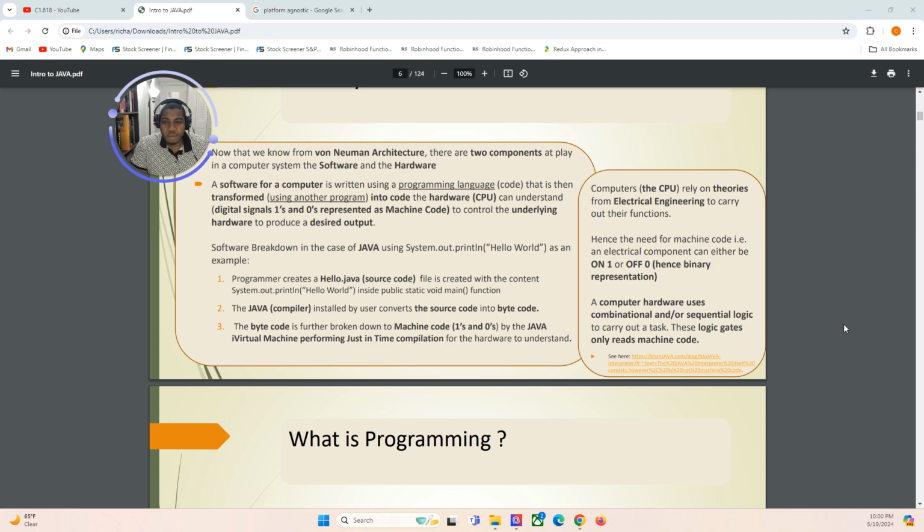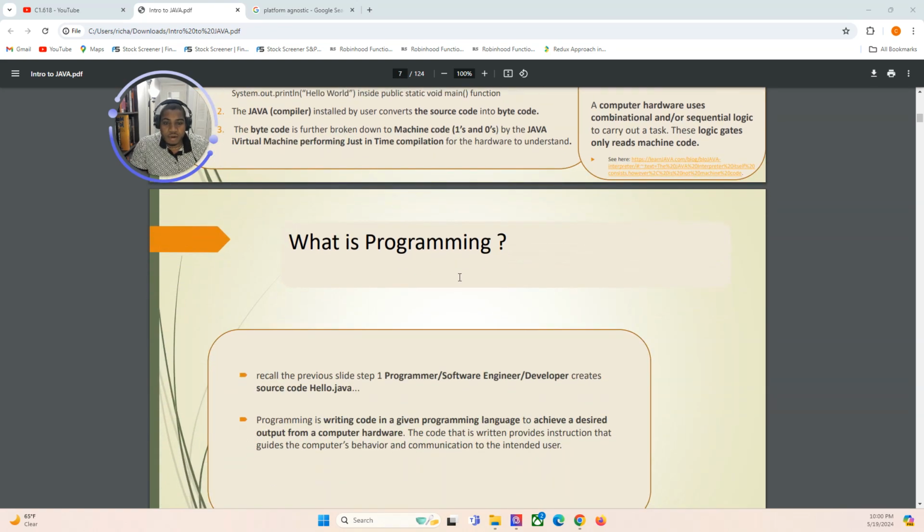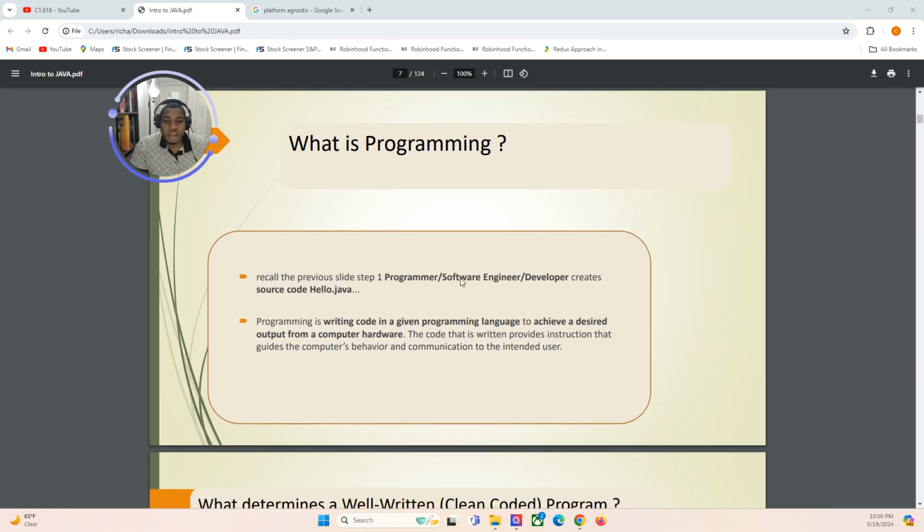And if we dig a little deeper, right, the underlying hardware is from electrical engineering theories, right? So combinational and sequential circuits, right? So these are logic gates. So a combinational circuit doesn't have any clock, right? Sequential needs a clock, right? So you need some timer there. So the series of these coupled together is what creates our CPU, right, or central processing unit, right? So combinational, sequential logic, they read in the data and manipulate the bits to provide the intended output for the user.